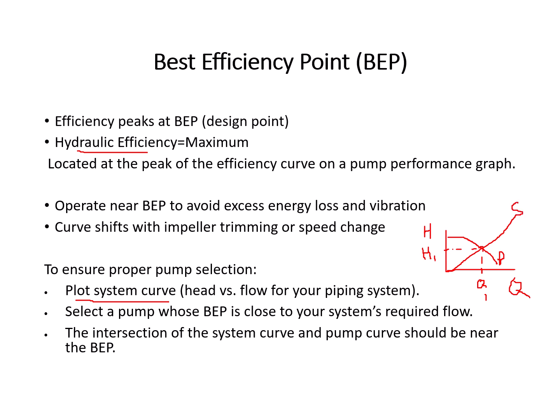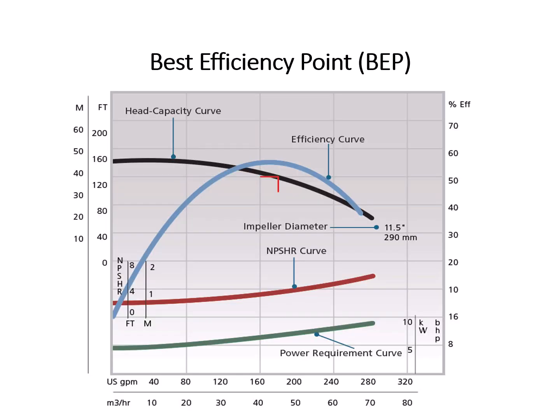And you may have the efficiency curve of the pump. So this is the best efficiency. You should select your pump such that the best efficiency is around or near your design flow rate. Okay, we will see this better in coming slides. Let's see. This is the efficiency curve for that particular pump.